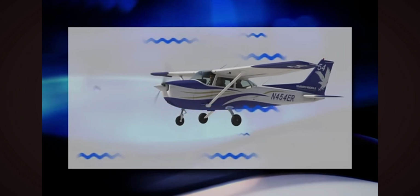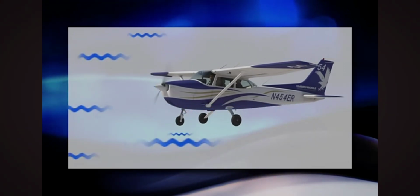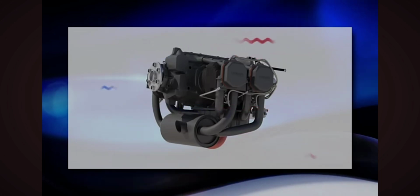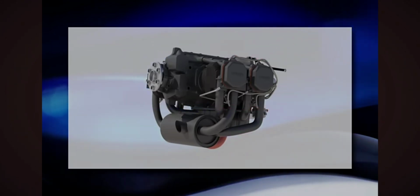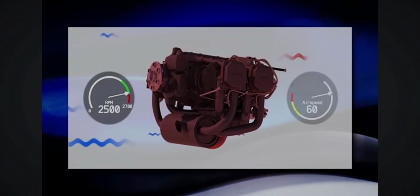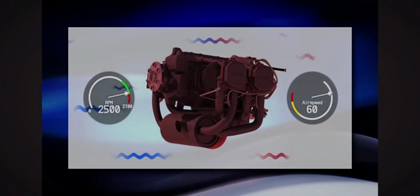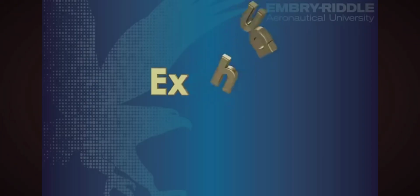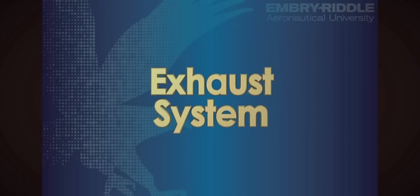However, we also use air to cool our engines. As the airplane flies through the air, outside air flows through inlets usually found on the front of the airplane, like the Cessna 172. This outside air is colder than the engine, so as the air flows over the engine, it cools it in the same manner that the oil cools the engine. This method of cooling can be severely restricted, however. When the airplane is running at high power and at very low speed, such as when climbing, airflow is minimized, causing higher temperatures.